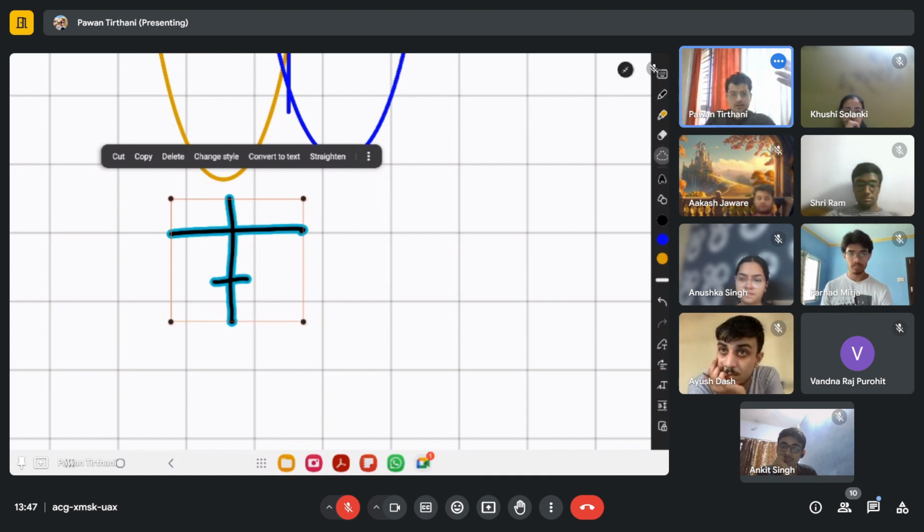Yes. More of the 90 hertz signal has been induced in my antenna. Now, the signal of 150 hertz modulation that I'm receiving, is it less deep? Yes. I'm receiving less of the right sector signal, or less of the 150 hertz signal.